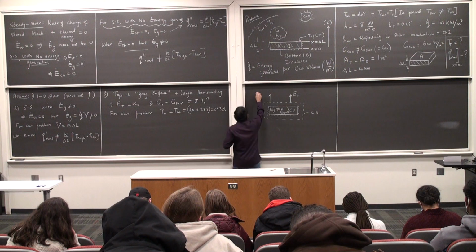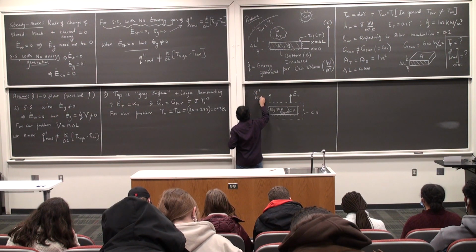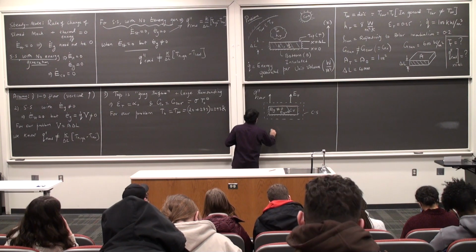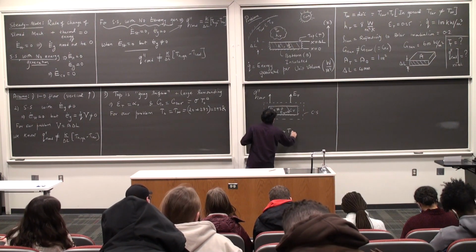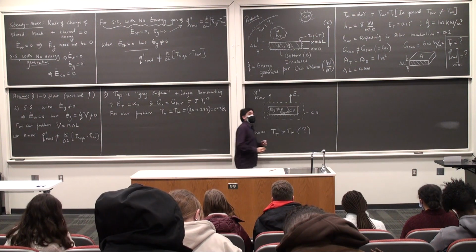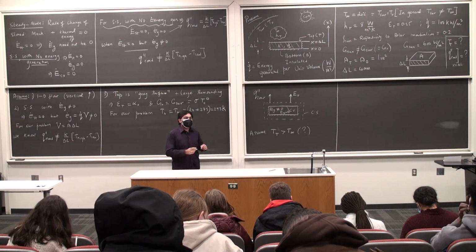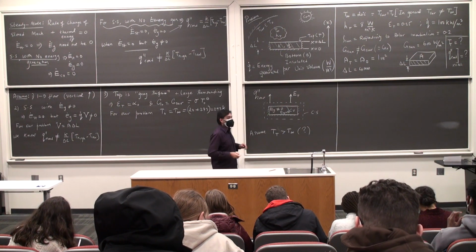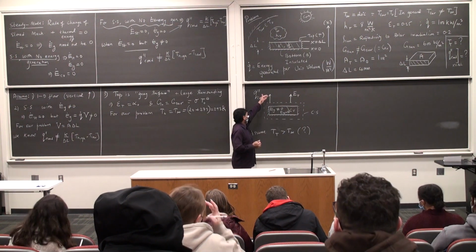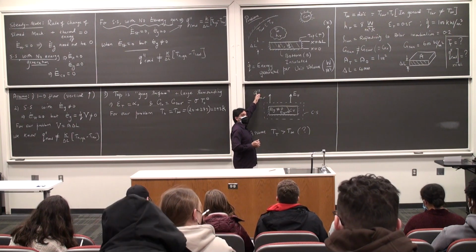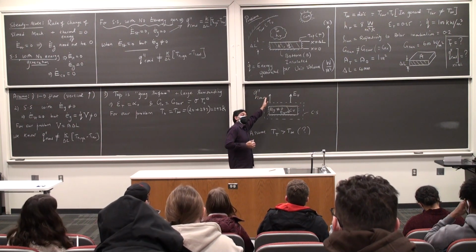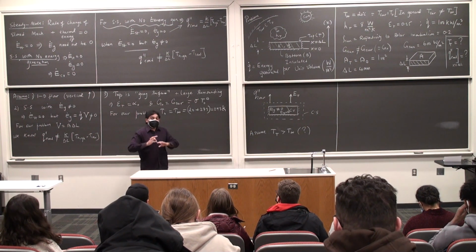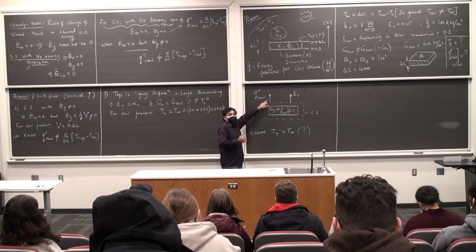Okay? So this is Q double prime convection. We don't know. Yes? What would happen if we assumed it to be entering the surface? No difference. Absolutely no difference. Because if it is entering the surface, then you'd just be flipping the directionality of this, and instead of being a term that comes in the E dot out, it will be a term in E dot in. That's all it does. So you're free to assume the direction of this.